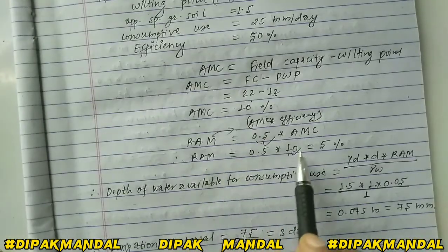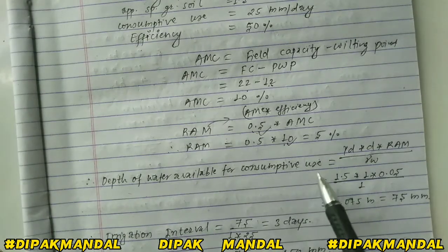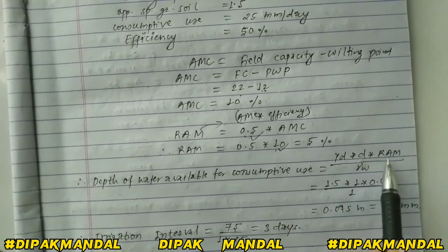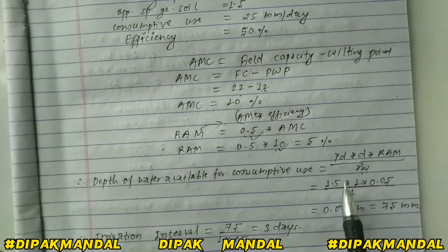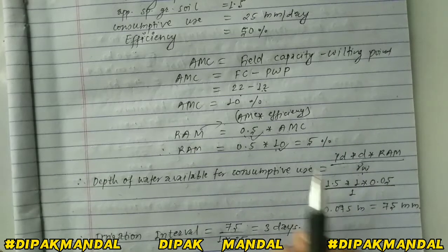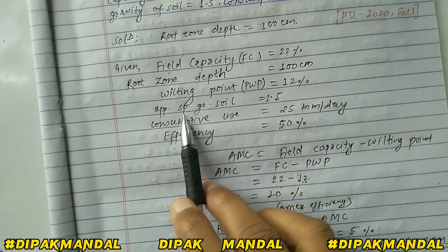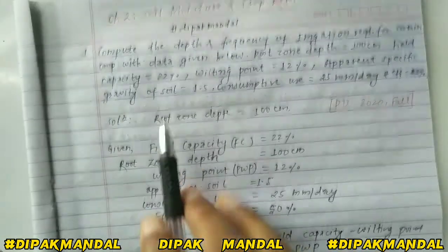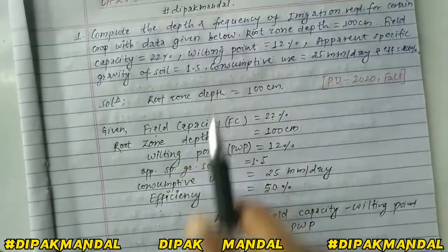So we calculated the value of RAM. Now we have to calculate the depth of water available for consumptive use. So depth of water available equals gamma dry into depth D into RAM, divided by gamma of water. Gamma of dry we have to take as 1.5, and in the question it is also given here. You can see here the apparent specific gravity of soil is equal to 1.5.